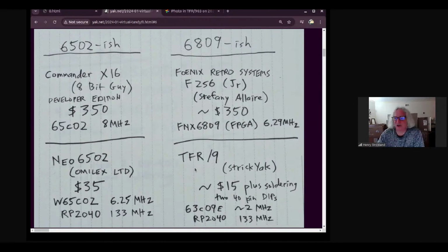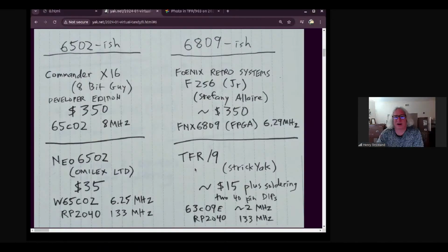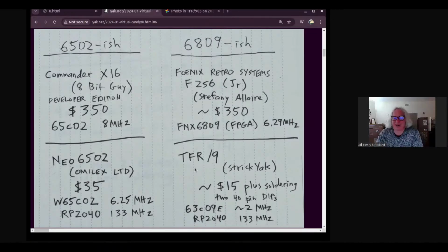But the deal is that the clocks are not coming out of a crystal. The clocks are coming out of code in the RP in the Pico. And sometimes that code has more work to do than other times, like if it's doing a disk access, and then I go and send a lot of data around and the clock quits running.